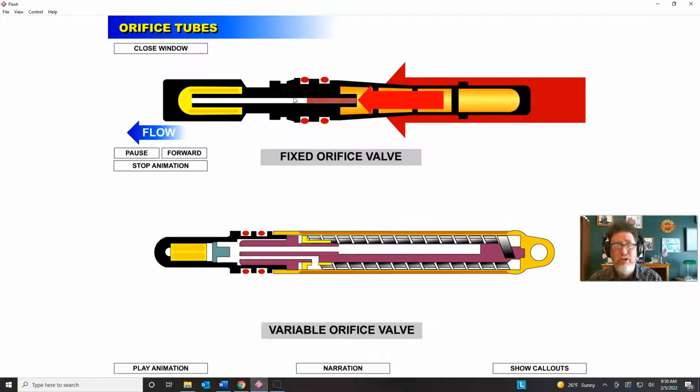And these tubes are sometimes not easy to get out. Sometimes there are special tools to pull them out. Sometimes you pull them out and they break in two, and that's terrible. Sometimes you're pulling it out from the short end, sometimes from the big end, depending upon which side of the connection the orifice tube is in. So I tell the students, you can put an orifice tube in 4 different ways. You could put it in this way first, or you could put it in this way first,